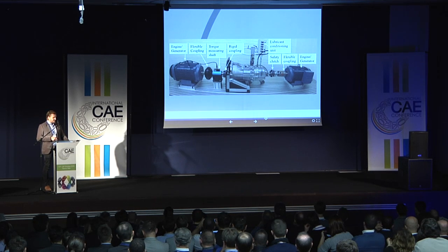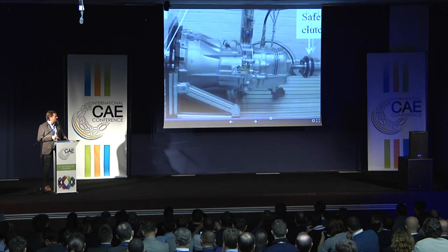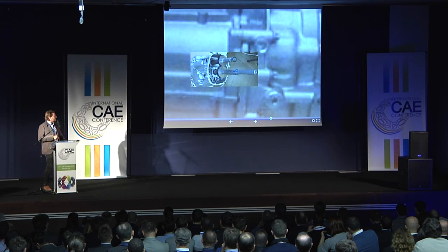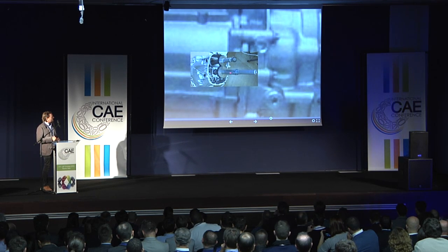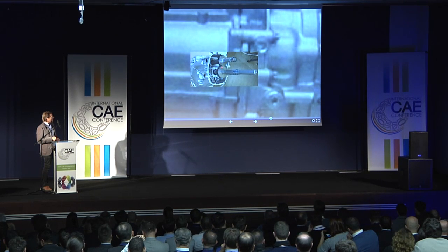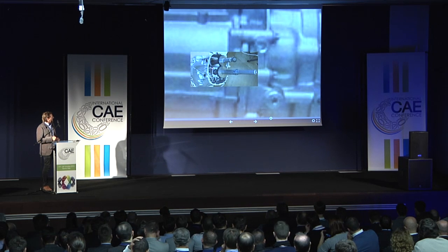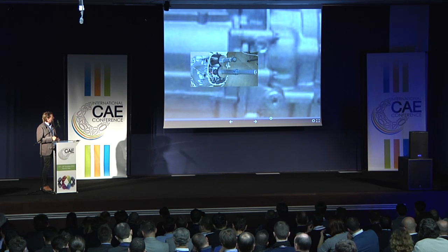Okay, let's take a look inside the gearbox, because this is the place where the dynamic bearing force is measured. So what you see is, I removed this part of the gearbox to get a look at the shafts. So these are the two shafts. You might remember the multi-body simulation model. This is the same model, and we set it up right here. So this is the gearbox section, there is the bearing position, and right here is the dynamic bearing force measurement device.